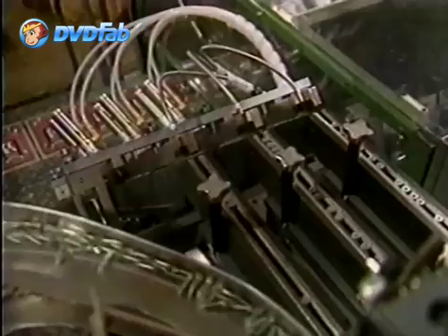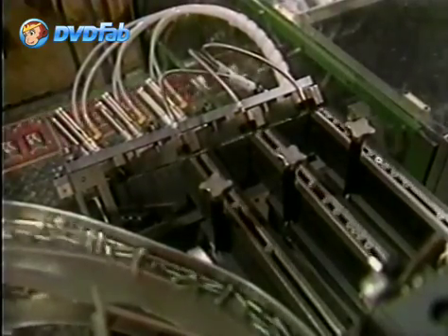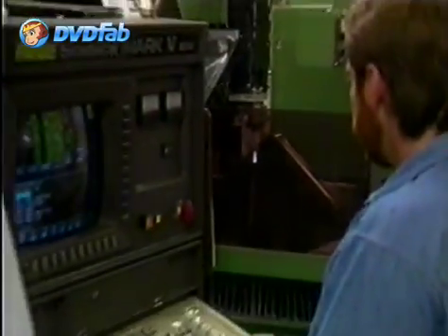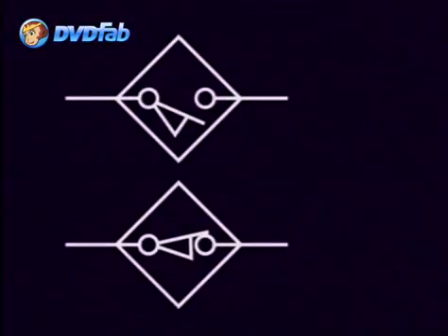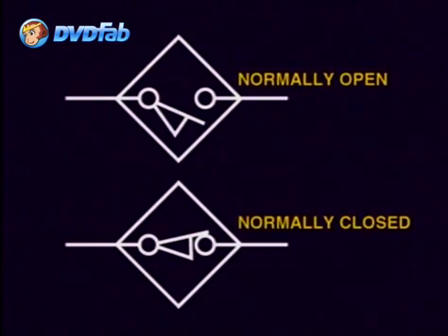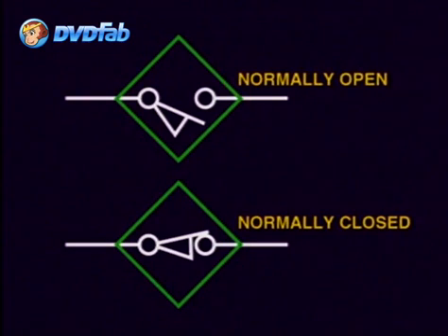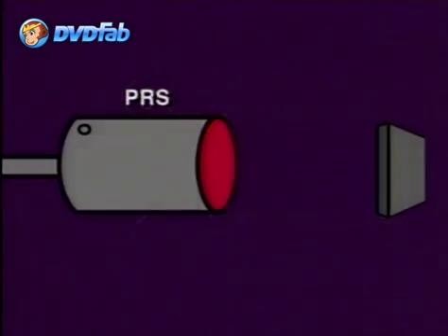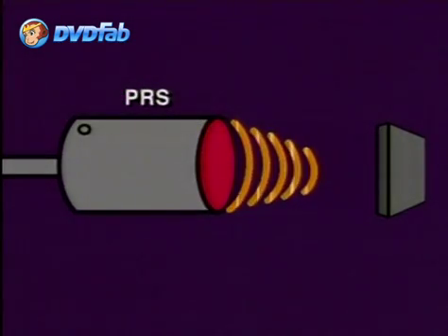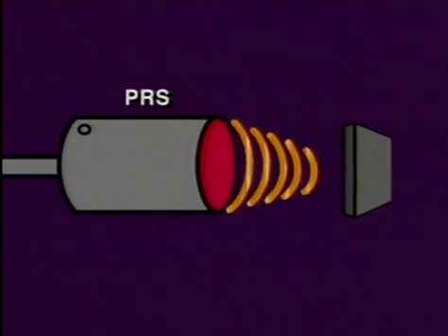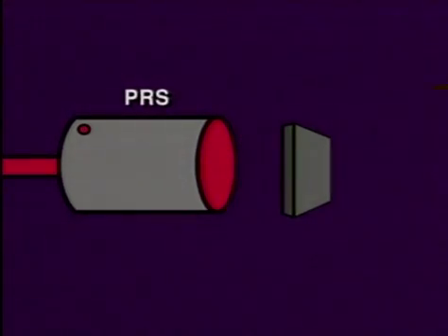Proximity switches are used in a variety of standard and harsh environment applications, requiring the detection of the presence of parts without physical contact. Proximity switches are represented by this symbol for normally open and normally closed configurations. The diamond-like symbol around the standard limit switch representation indicates a solid-state type of switch contact closure. The general operation of the proximity switch is basic. When a part gets close in proximity, the switch will detect it and will open or close its contacts.